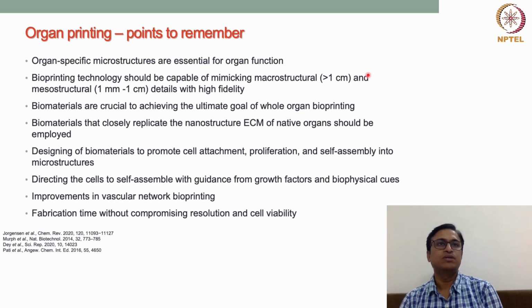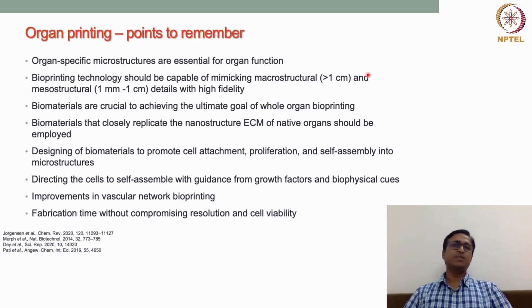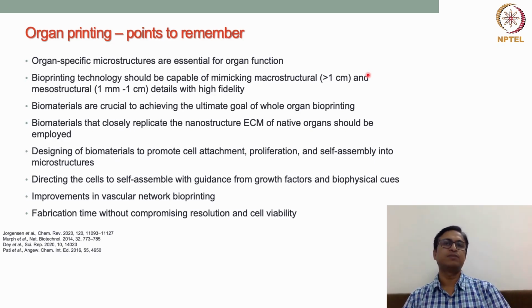But we should not compromise on resolution or on cell viability, because if we want to improve print fidelity, we have to increase the viscosity. And with increasing viscosity, a very stiff microenvironment is not good for cell viability. So that's what we have.